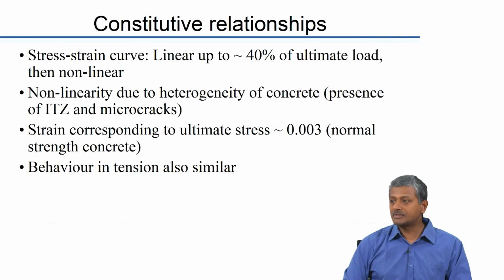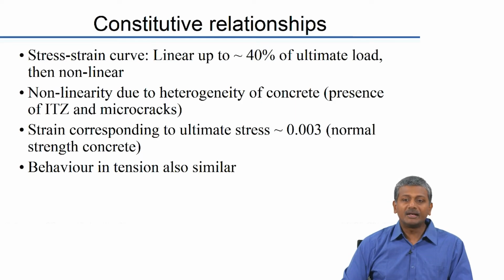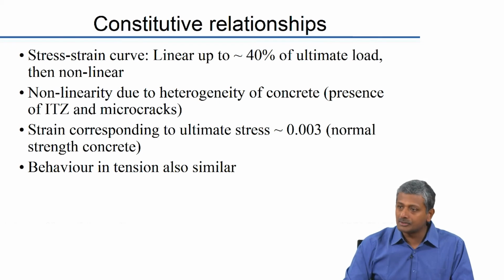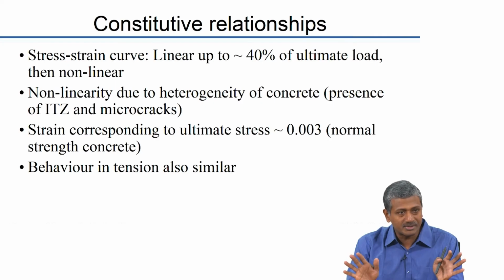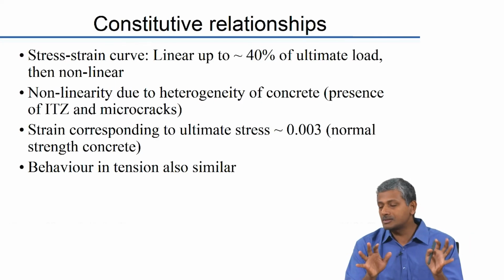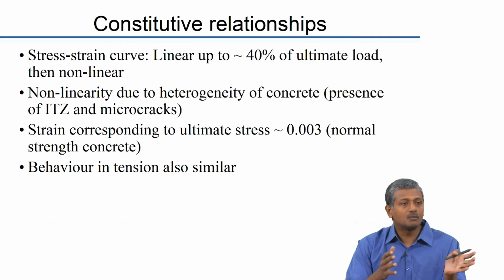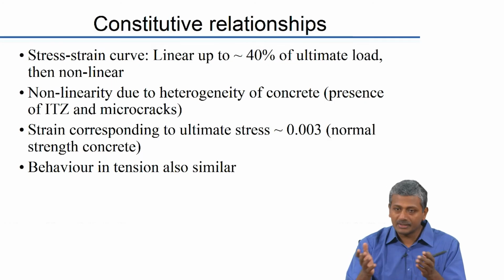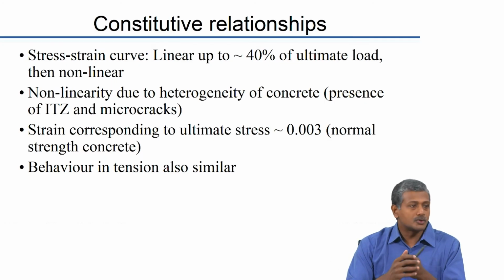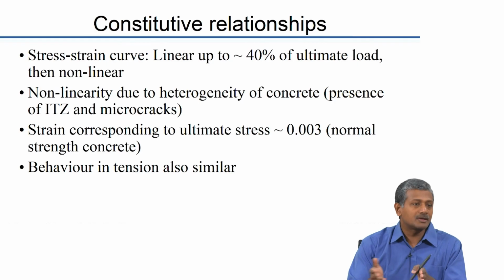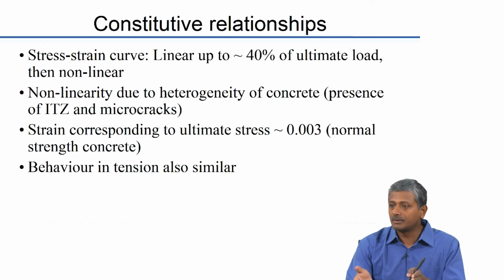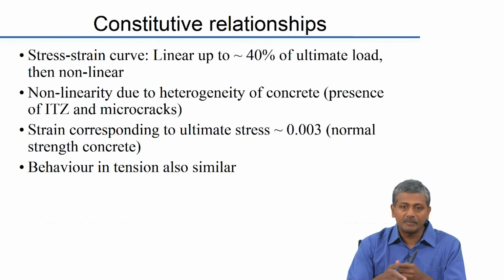So, again, as far as understanding stress strain characteristics of concrete are concerned, we know that at very low load levels, concrete is almost elastic. Typically, we assume that the elastic nature of concrete or sometimes the linear nature of concrete, both are not the same, right. You understand that linear and elastic is not one and the same thing. What is linear? What is elastic? Elastic means it has the capability of coming back to its original shape. Linear simply means the graph is linear or proportional, right. The stress is proportional to strain, that makes a linear graph.